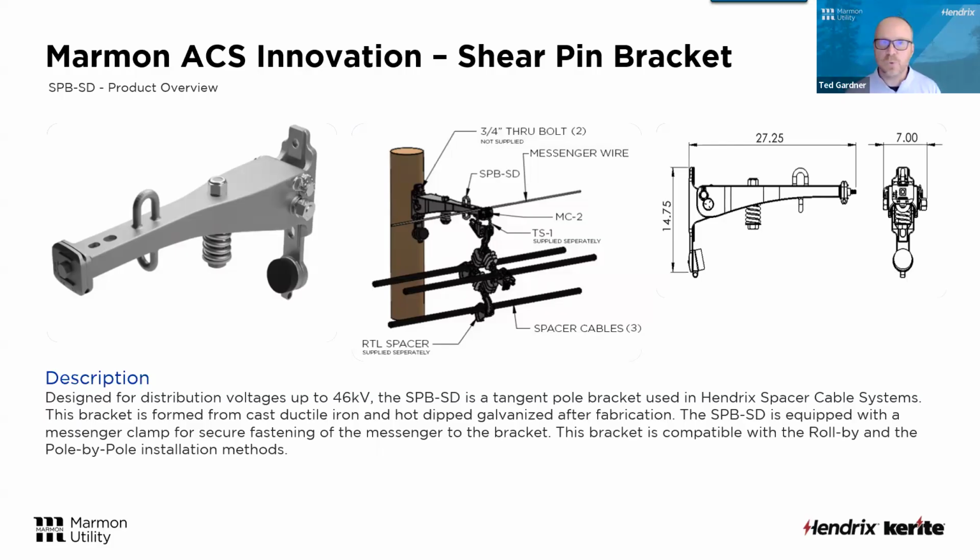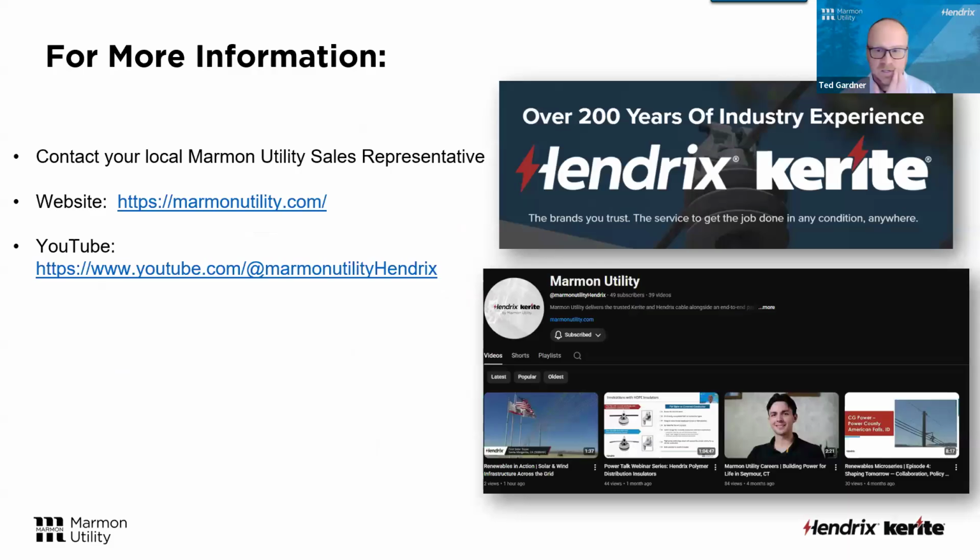So we're seeing more and more heavy poles, ductile iron, steel poles, even some concrete poles in some cases, fiberglass composite poles that'll give you a little more flexibility. And when you think about a system being super rigid, that tends to lean towards more breakage, more damage. Whereas if we get a little flexibility in that, like with a shear pin bracket pole or a flexible pole, it makes it a stronger system. So this is one of the things that's available. And if you want more information on that, you could check that out on our website.